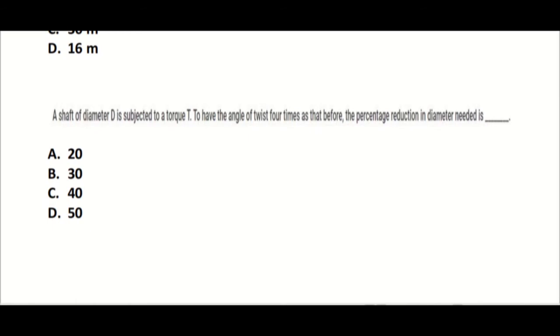A shaft of diameter d is subjected to a torque T. To have the angle of twist 4 times that of before, the percentage reduction in diameter is?